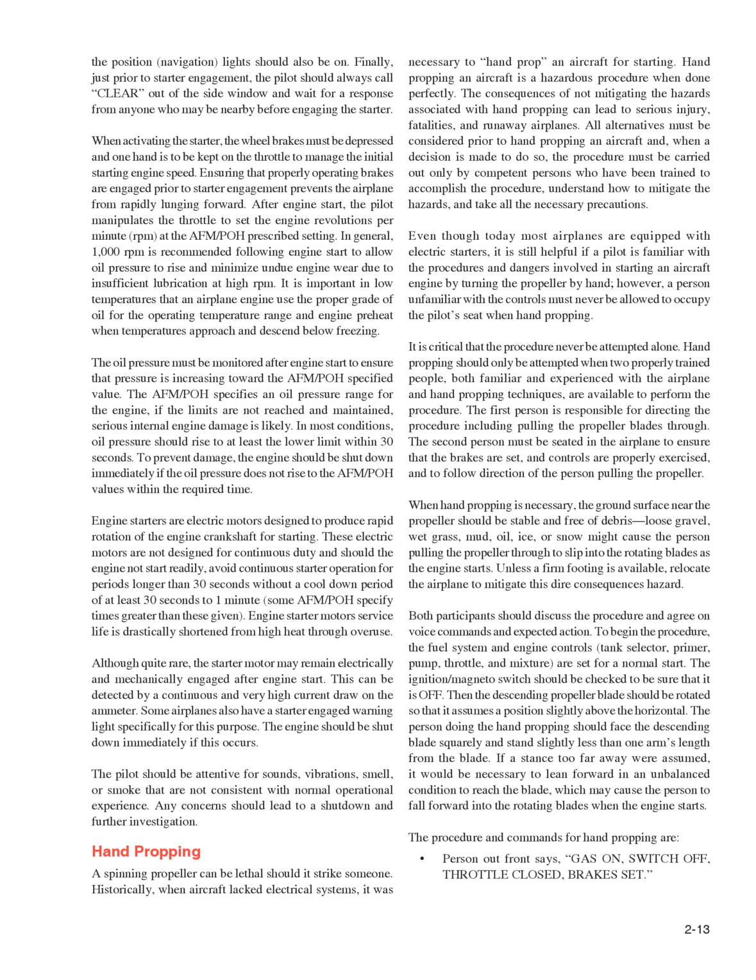Although quite rare, the starter motor may remain electrically and mechanically engaged after engine start. This can be detected by a continuous and very high current draw on the ammeter. Some airplanes also have a starter engaged warning light specifically for this purpose. The engine should be shut down immediately if this occurs. The pilot should be attentive for sounds, vibration, smell, or smoke that are not consistent with normal operational experience. Any concerns should lead to a shutdown and further investigation.